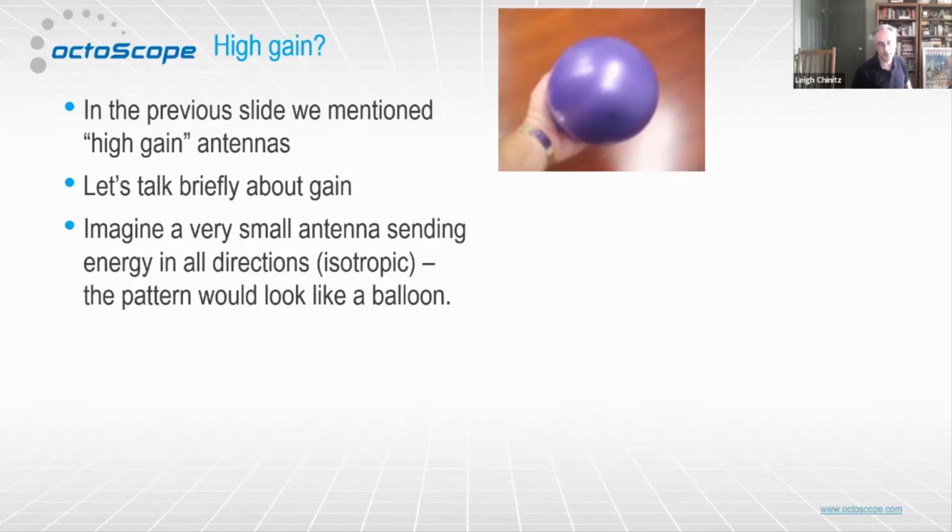As that antenna gets smaller and smaller, that donut gets fatter and fatter. And if you go all the way down to a point antenna, you can imagine the energy being radiated out into just a big sphere in all directions. It's not a real thing, but it is the mathematically perfect antenna that people in the business like to use as the default model.